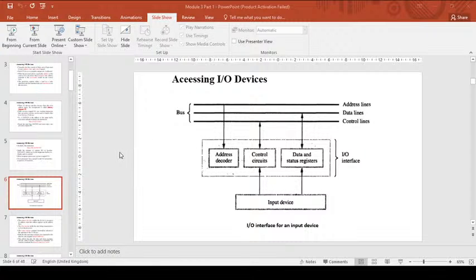Now there is one more task. It is also told to store it in the memory buffer. So, move R1 comma R0 plus. In the processor register R1 there is a character, right, which is entered and then displayed. R1 has the data. From the R1 register it is transferred to some memory location for storing. Which memory location? The one R0 holds. R0 holds the location indicated by the address label line.